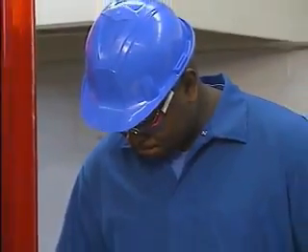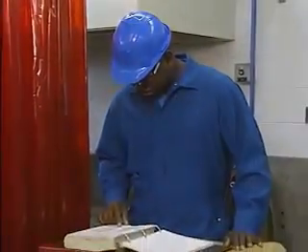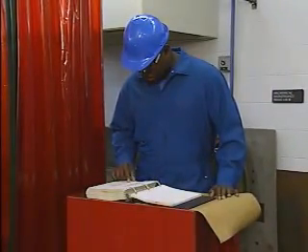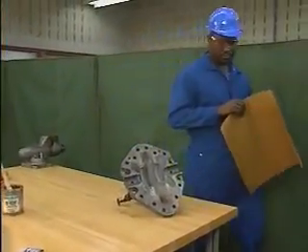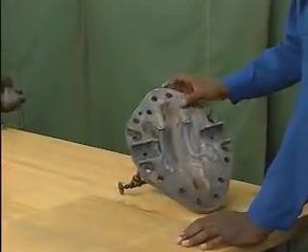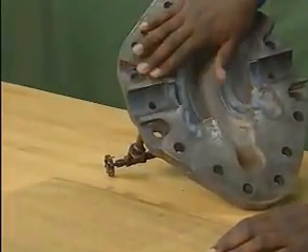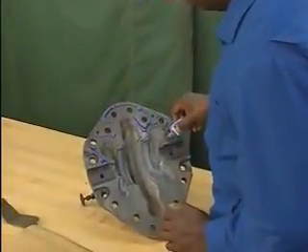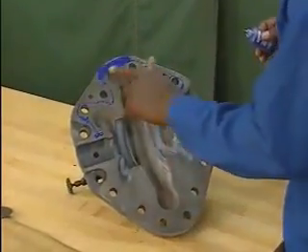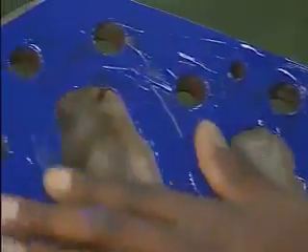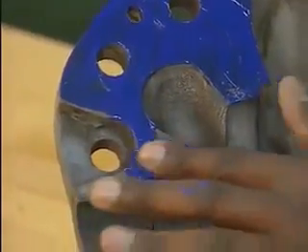First, the mechanic must verify that he has the correct gasket material. He refers to the pump manufacturer's manual for information about the gasket material that should be used. After the mechanic obtains the correct gasket material, he must accurately cut a gasket to fit the shape of the sealing surfaces. In order to do this, he must transfer the shape of the sealing surfaces to the gasket material. This can be accomplished by coating one of the sealing surfaces with a substance that will transfer easily to the gasket material. In this example, the mechanic coats the sealing surface of the upper half of the pump casing with a type of dye called bluing.